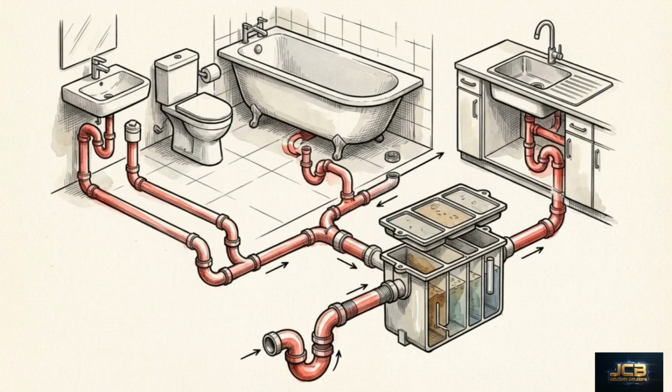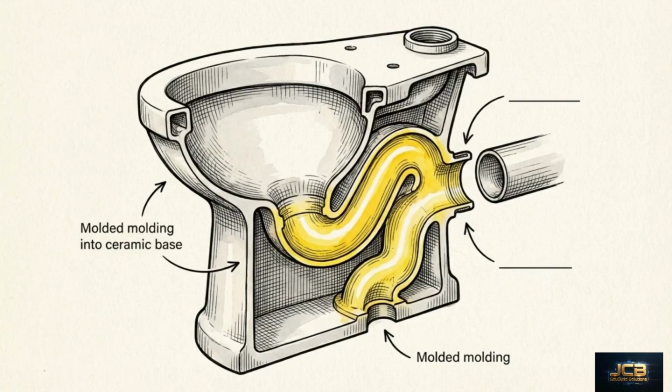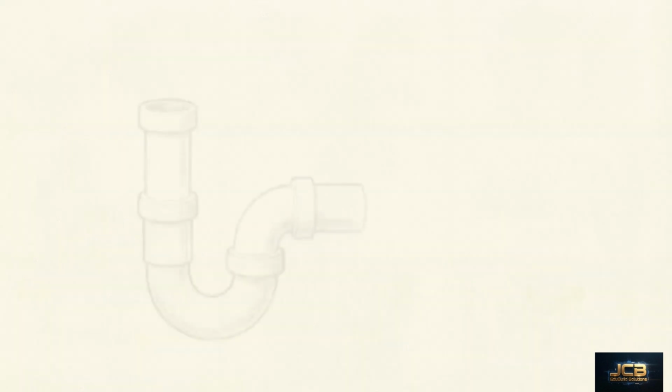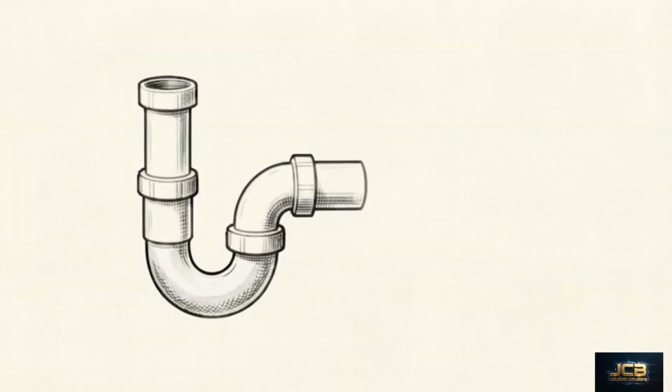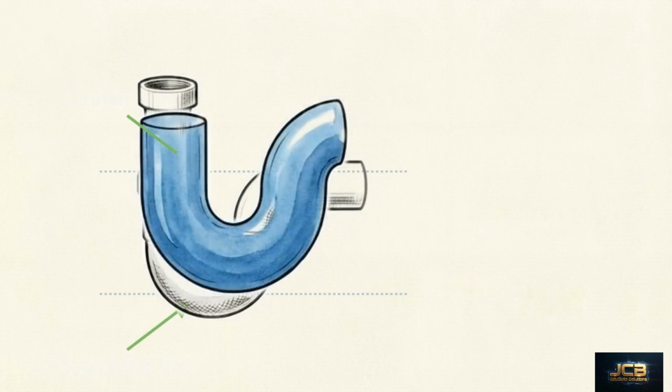Every single plumbing fixture must be separately trapped by an approved water seal trap, unless the fixture possesses an integral trap of its own. To calculate the required liquid volume, we define specific anatomical landmarks on the pipe geometry. The upper boundary is the crown weir, the lowest point of the trap's internal upper curve. The lower boundary is the top of the dip at the base. The trap seal is the maximum vertical depth of liquid retained precisely between these 2 points.